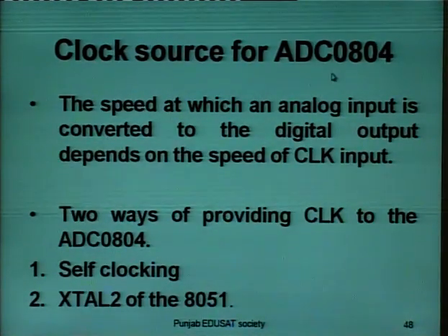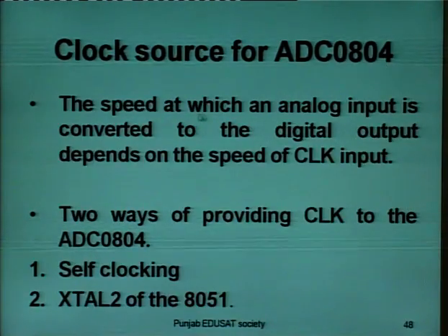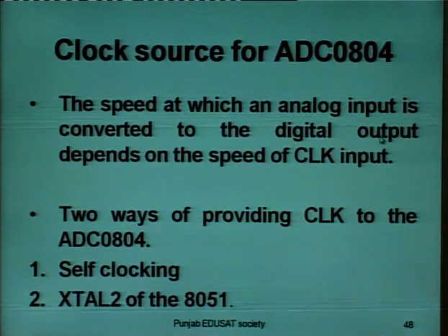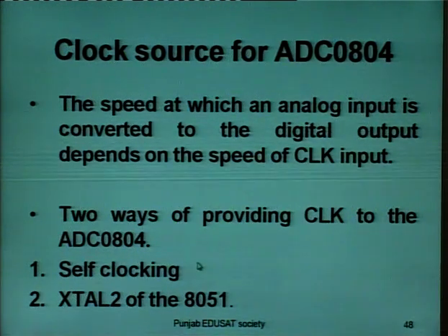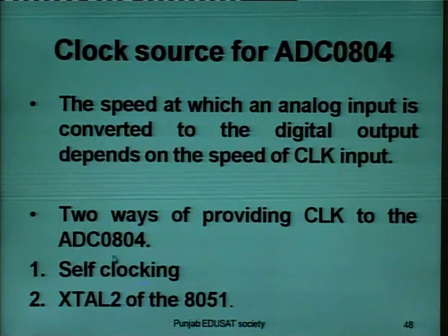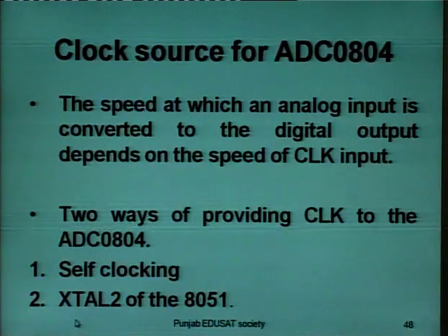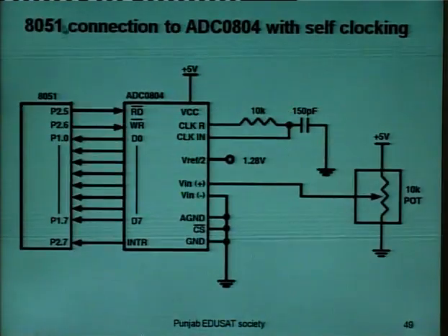Clock source for the ADC 0804. The speed at which an analog input is converted to the digital output depends on the speed of the clock input. There are two ways of providing clock to the ADC 0804: self clocking and from the crystal of the 8051.